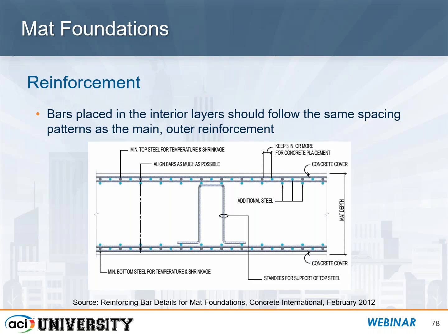And here are some recommendations. We'd like to try to keep the spacing, especially if you have this double layer of mat, the same in both mats, or keep them such that you space it out every other bar. The reason for this is, especially if there's a lot of reinforcement, you'd like to keep enough channels open for the concrete to flow very easily into this relatively thick mat.